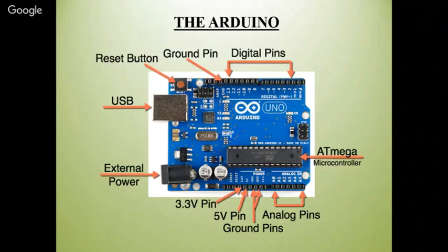If the servo motor or stepper motor has a load, you have to use servo drivers or stepper motor drivers, otherwise your Arduino board will burn, and there is overload on the computer also. So this will happen.